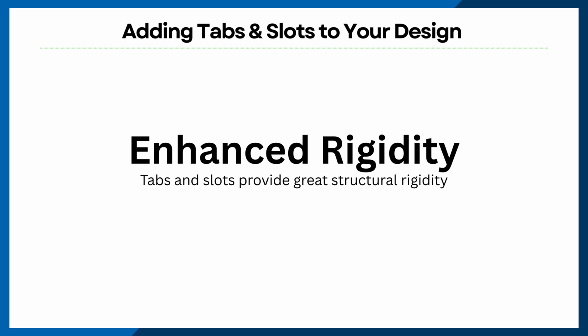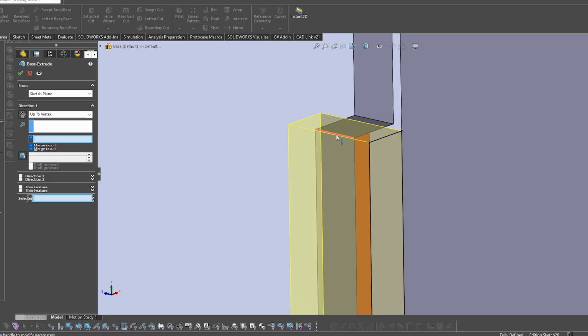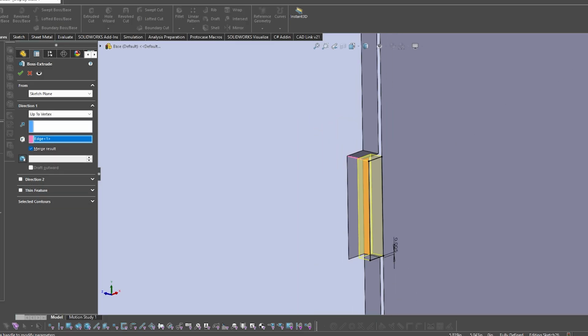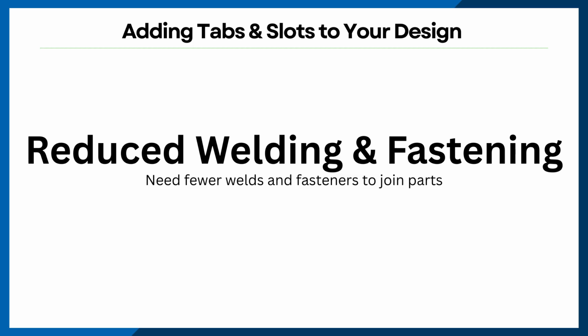Enhanced rigidity. By locking two or more pieces of sheet metal together, tabs and slots provide better structural rigidity. The interlocking nature of these features prevents movement and creates a much more robust connection compared to relying solely on welds, adhesives, or fasteners.